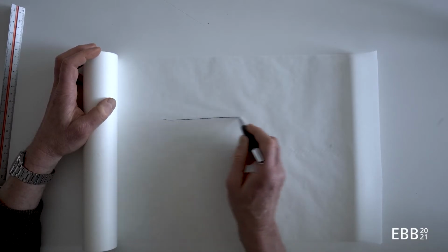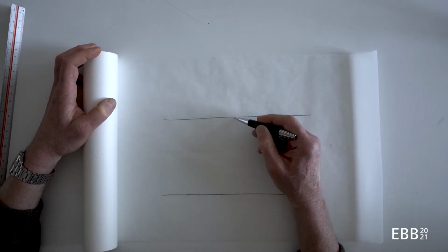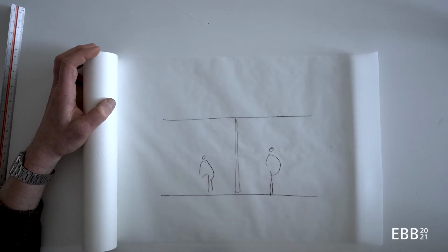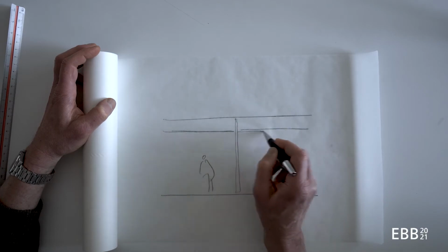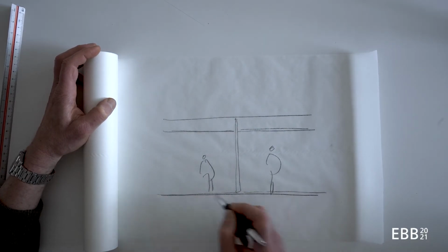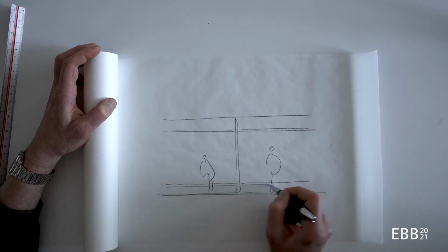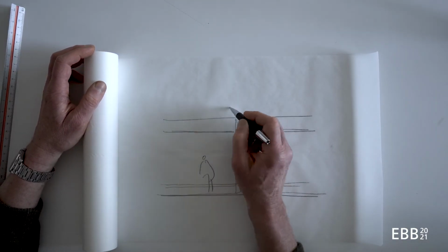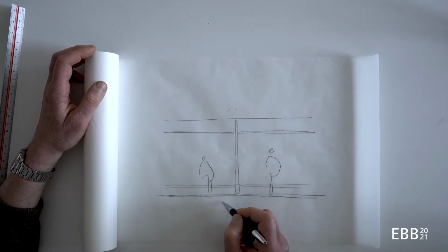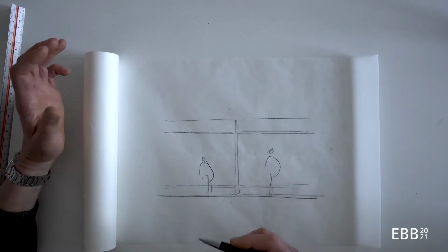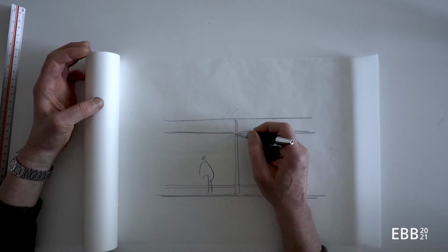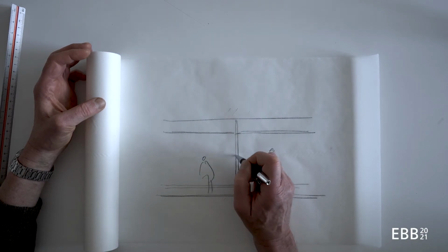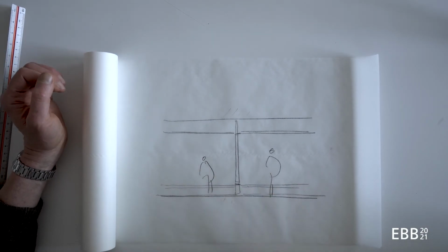So one problem is that you want to make spaces airtight, but you might have suspended ceilings, and you might have screeds, or even double flooring. And the acoustic performance of the separating walls is much better if you go right to the concrete, but the building becomes much more flexible if you stop the separation at the suspended ceiling or at the double floor.